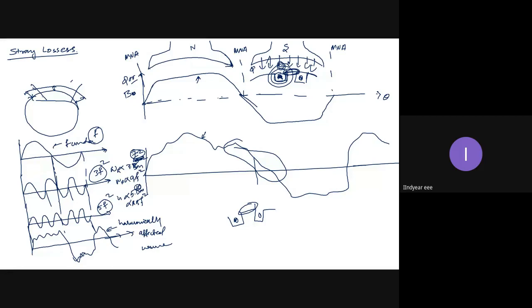So iron losses in the core are increasing because of harmonics. That is the reason why everybody is worried about harmonic content present in the current wave. We should never allow harmonic content in this current wave. It should always be kept at a very low or no harmonic content condition, because they will increase iron losses in the entire system to a very large extent. Though they are less in magnitude, their frequency components are more, and they are quite prominent. So these will form the additional losses in the machine, which are part of stray losses.